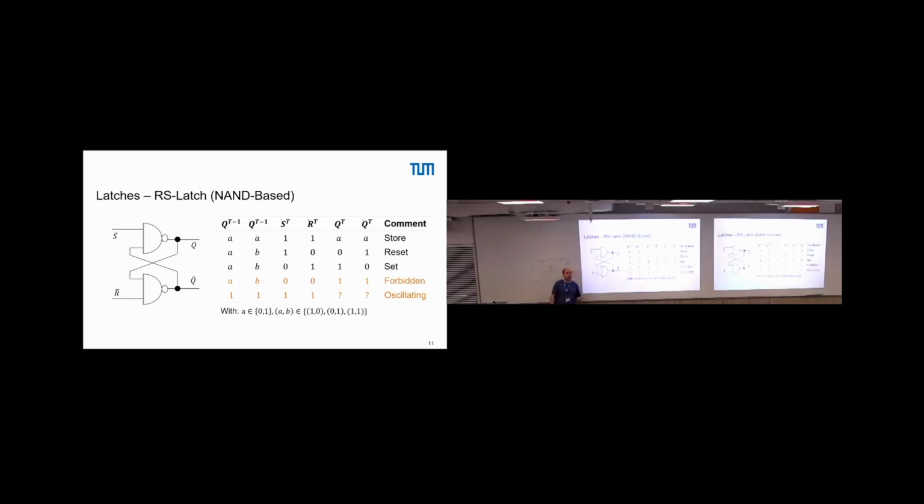Most of the time in digital circuits, we want to be synchronous for good reason, because we can then do timing simulation, we can predict how a circuit behaves, we can be sure that a circuit at the end is functioning. And we can break down our whole circuit design into clock cycles and not simulate all at the same time. Which makes it, from a tooling perspective, very interesting to have a synchronous circuit, because then we can use all the tools we have today. And only with them we can design really complex circuits.